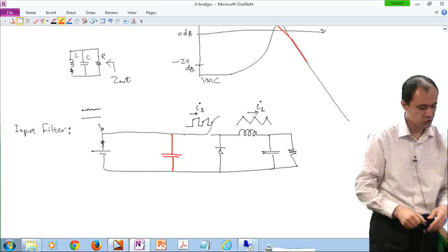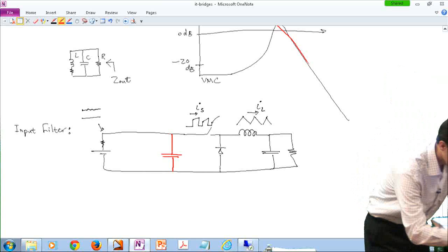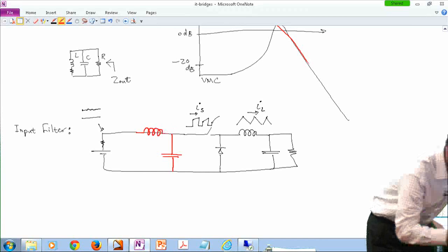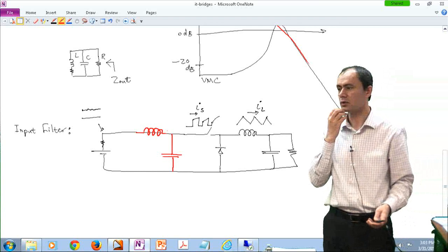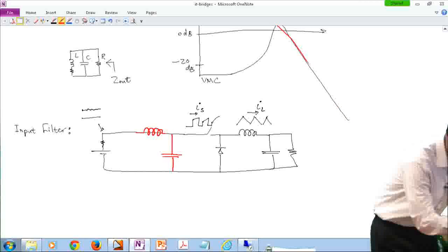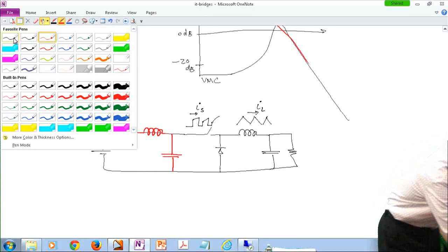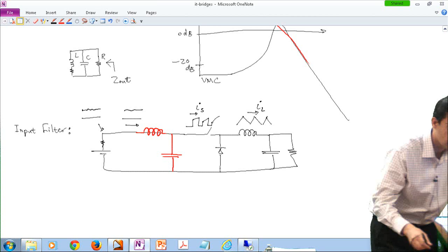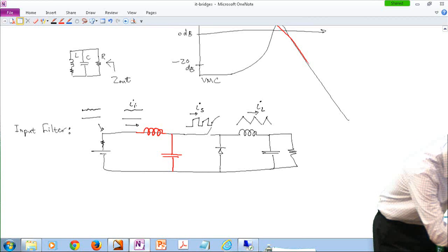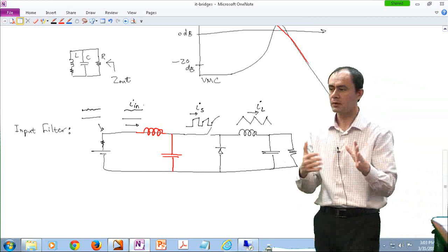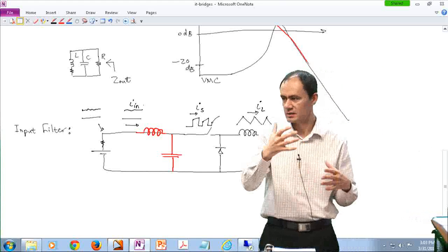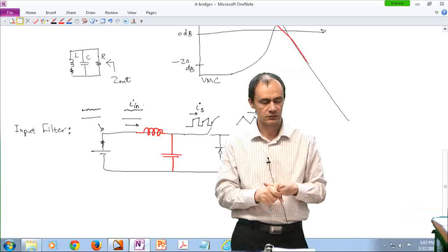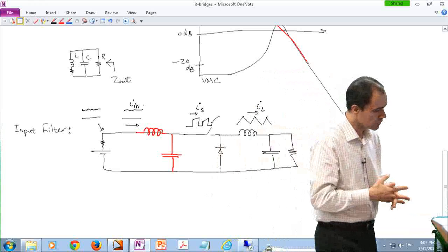But sometimes you may say a first order system, which is this cap, is not enough for me. I want to actually make the current even smoother and place an inductor here as well. So it's like a second order filter, okay? So in that case, your input current, again, depends on the size of the components that you're using. It is almost a DC current. And therefore that problem that we have goes away. So if you have other elements connected to the source, they are almost seeing basically a DC current or DC voltage. All right.